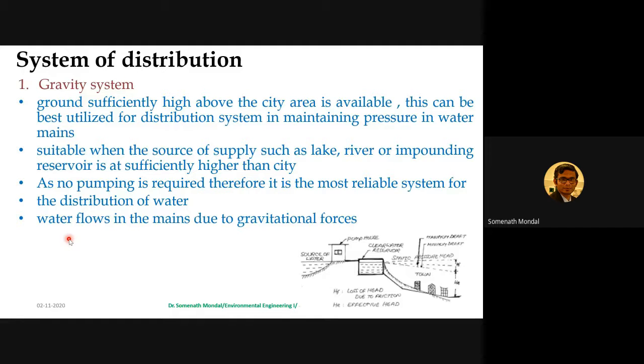So our clear water reservoir is also located here, and in this case we need not construct overhead tanks, which we'll be discussing later on, to get that additional pressure. We just simply construct the freshwater reservoir tank at ground level. And from there, since we are getting the pressure head, the water is drawn over here, and then you have the buildings, and you can see that in this case the pressure will be maintained easily.